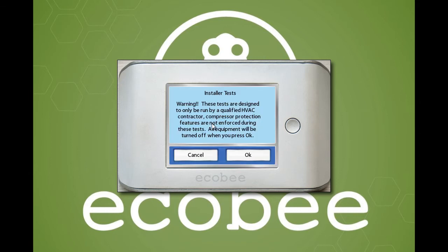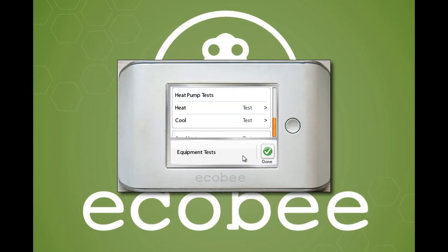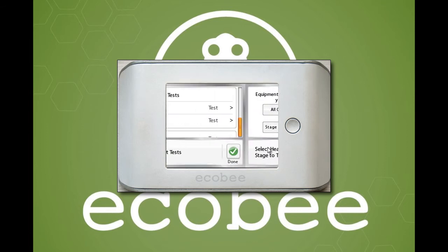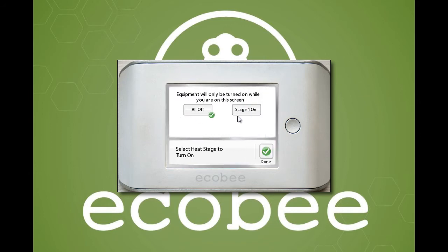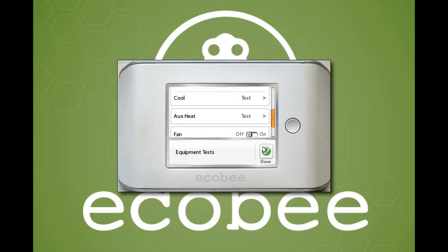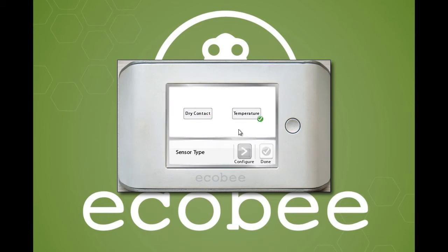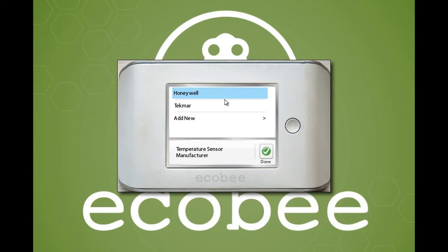The test mode allows you to directly engage the relays and verify operation, giving the installer peace of mind everything is working as configured. If you have a remote sensor module connected, these 4 inputs will appear. By giving them a name and configuring the type of sensor, you will enable the input. The remote sensors are not included with the module and can be purchased directly from your HVAC wholesaler.